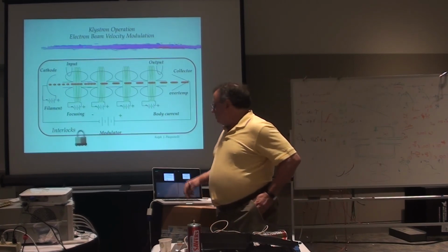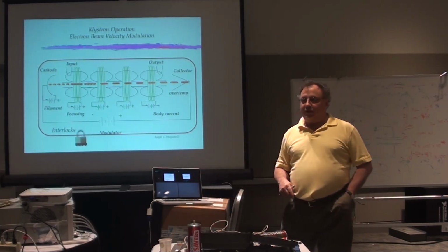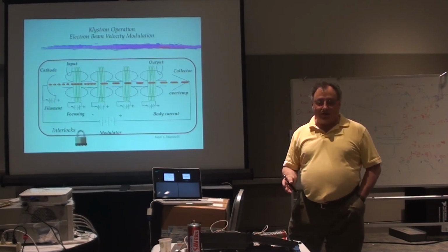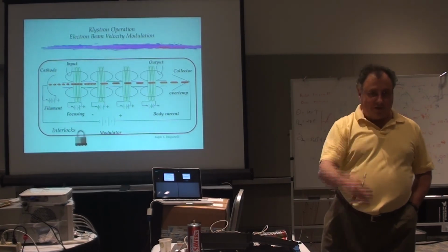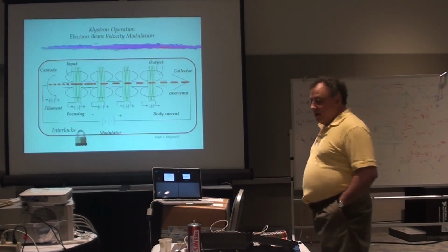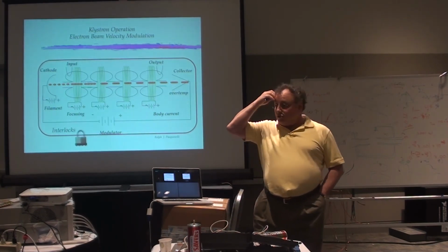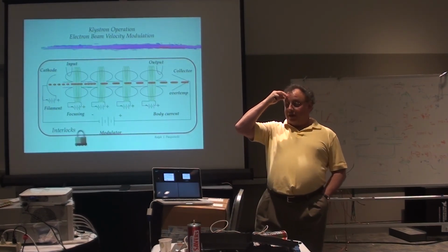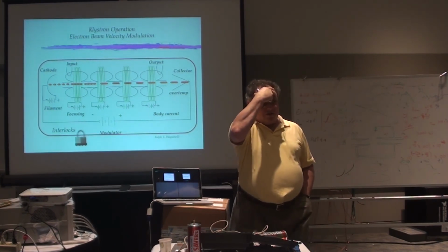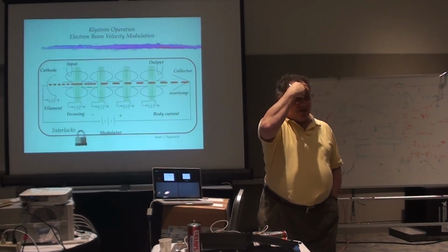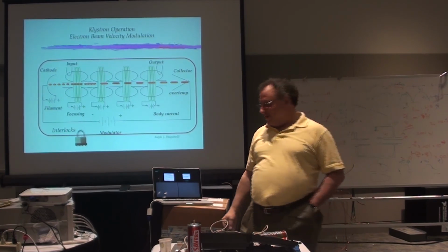What typically will go bad on a klystron is the cathode will eventually become depleted. But these klystrons we installed in the 1990s in our 805 megahertz cavity prototype from the LINAC can last well over 100,000 hours. There's still, I think, at least one that's original from 1993. It's amazing. Everyone talks about longevity of solid state. A well-designed tube lasts a long time too. That's over 20 years out of one tube.